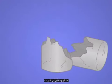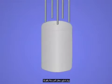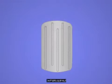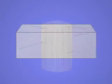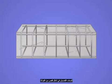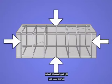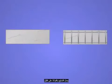This sudden type of failure is unacceptable in structural applications, and most concrete is reinforced with steel to increase its strength and ductility. In practical applications, bars are added in a steel cage pattern to cross potential planes of tensile failure. Steel reinforcement serves to limit crack formation and crack widths, increasing the life of the structure.